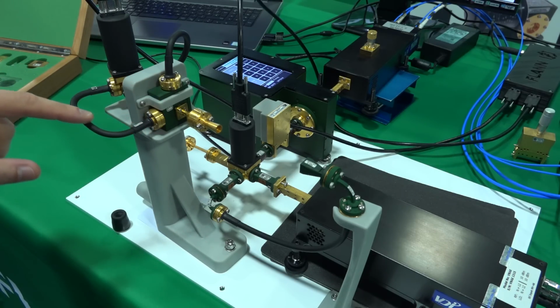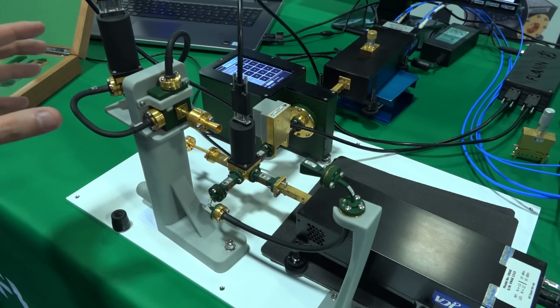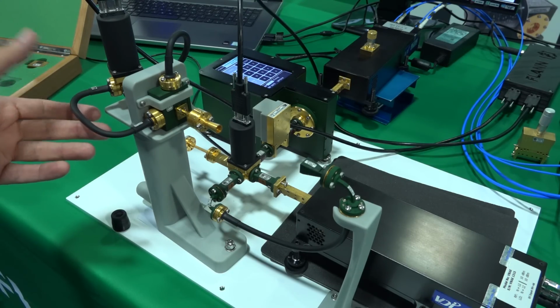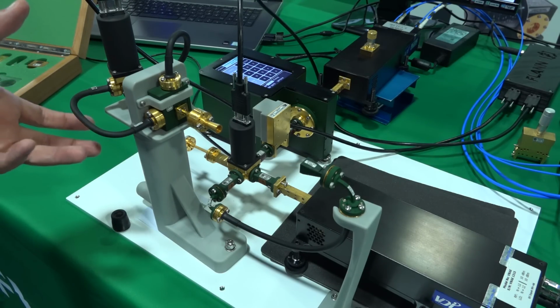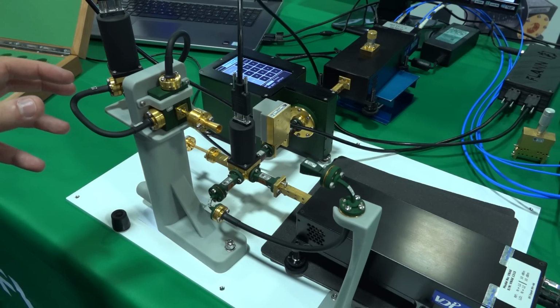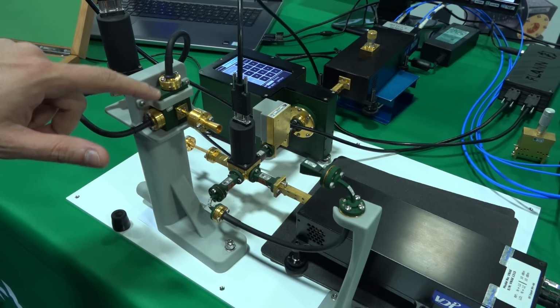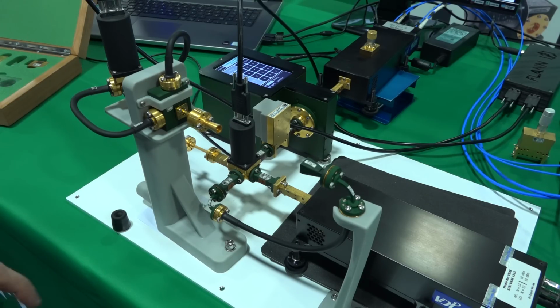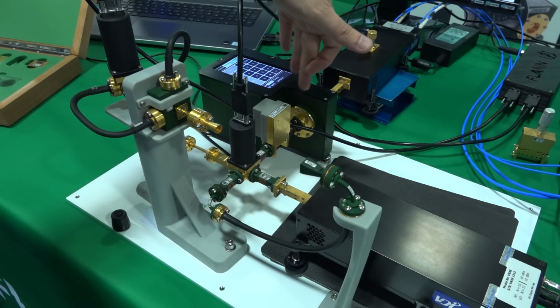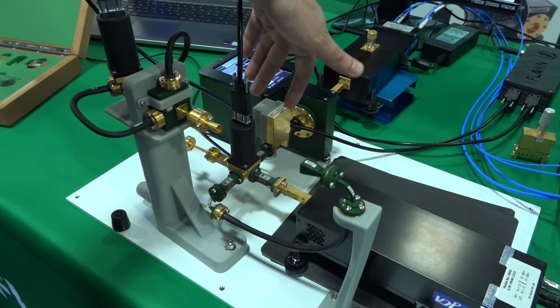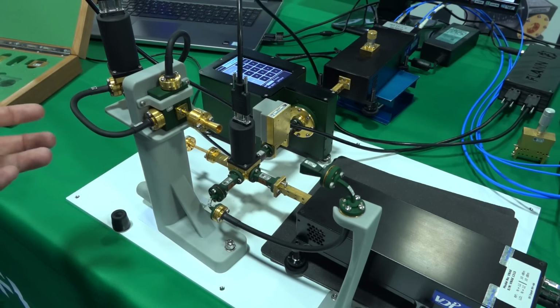They do have these flexible waveguides that you can flex a few times and set into place, but they still will have essentially the same loss characteristics as a regular piece of waveguide, but now you have the complete freedom to bend them in these unusual angles once you want to set up your setup and then fix it in place. We do have a full band OMT conversion, which is also pretty new. We do have two different attenuators here, a precision attenuator and a piezoelectric driven attenuator, which is also really, really small, making things compact at D-band.